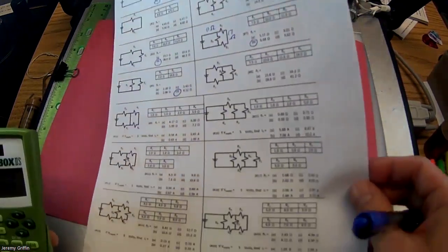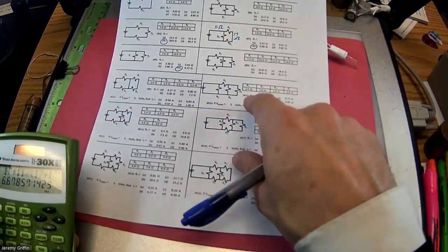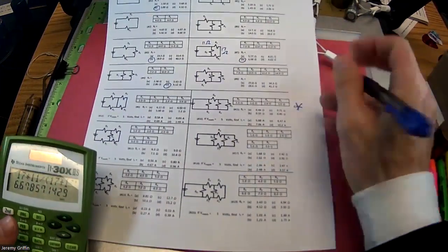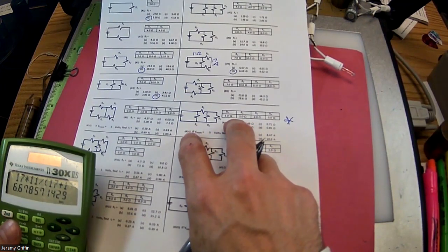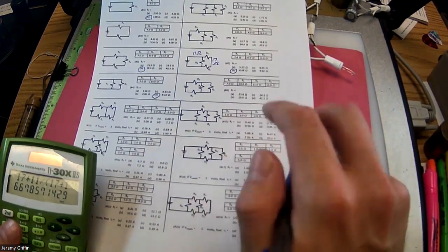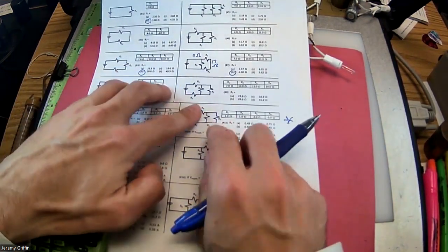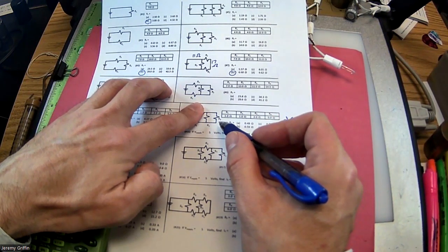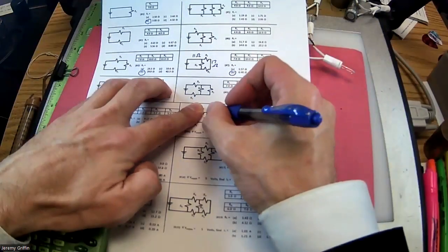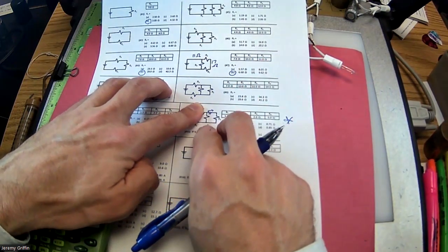All right, let's jump down, I want to do one of these down here. Let's do this one right here. There's actually a pair of questions. So what's the resistance? But then after that, what is the total current going through? Right, so you guys see R2 and R3 are furthest away from the source. So we're gonna start with those 2, R2, R3. Now those are in series or parallel? Parallel, right? You guys see how the current has to split at that point and get pushed through both simultaneously?